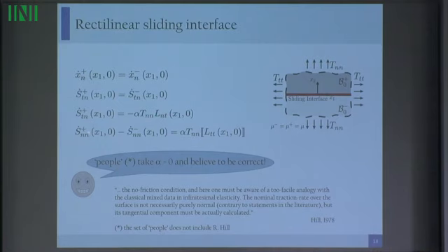Second, the last equation is also non-standard because people usually take the difference between the normal component of incremental traction to be zero, but here again they are a function of the Cauchy stress orthogonal to the interface. So we recover the usual conditions only if the component of the tension orthogonal to the interface is zero.